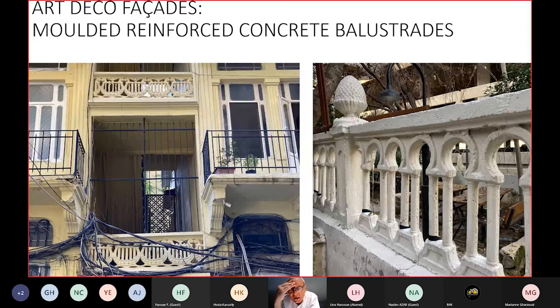When I say exceptional, I mean it the way it must have appeared at the time, because instead of bringing in stone and stone masons and all of this, everything could be done out of this cement and reinforced concrete, and it looked like something extremely solid, monolithic, that would stand the test of time, would be here forever in their idea. And even then, the red tile roofs were abandoned because those concrete slabs were really resistant to water. And we know today that it's not waterproof. We know today that we need, of course, other layers of waterproofing to protect it. However, at the time, it was really the new material.